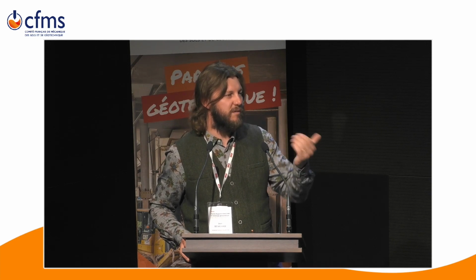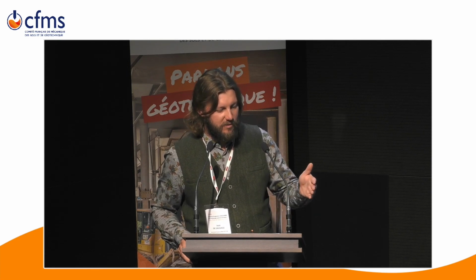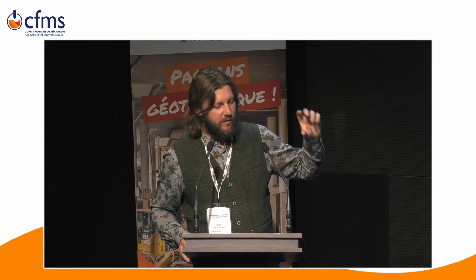So to change it, we glued some cement on the nails to change the rugosity of the nails and modify the friction law accordingly. But of course, you're right, it depends on the grain size. The problem is the friction law is always given as tau, the friction stress, as a function of the relative displacement, and the relative displacement is obviously not kept constant when you go to the model scale. So I think it's a very interesting problem that we have to work on. Thank you very much.